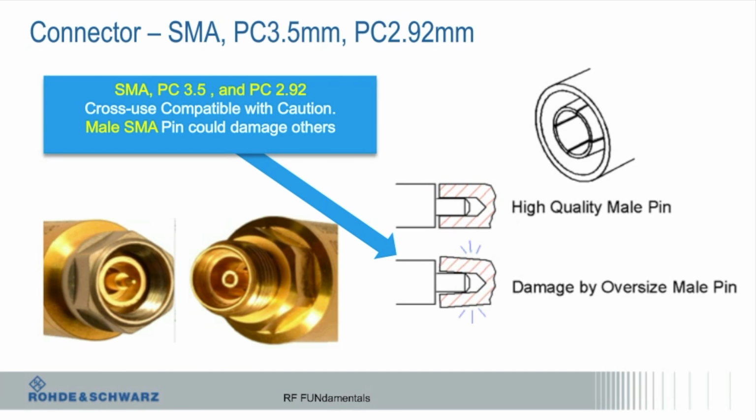What's that? How to detect that? Well, the main thing, you can't really see this once it's connected because obviously it's threaded. But if you look at this here, the center pin, you see there's like 4 little slots. If you looked at it carefully or under a microscope, I'm blind so I can't see squat.